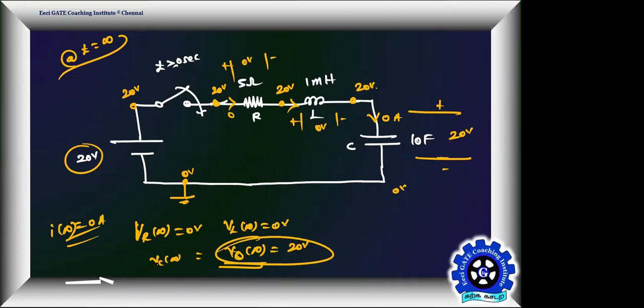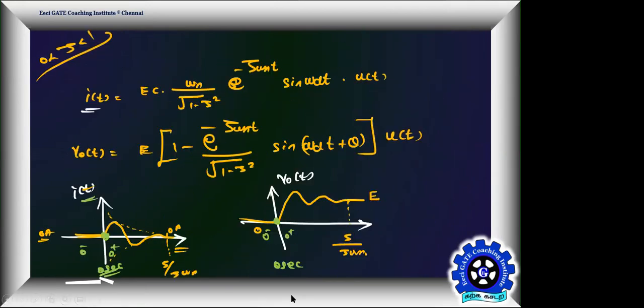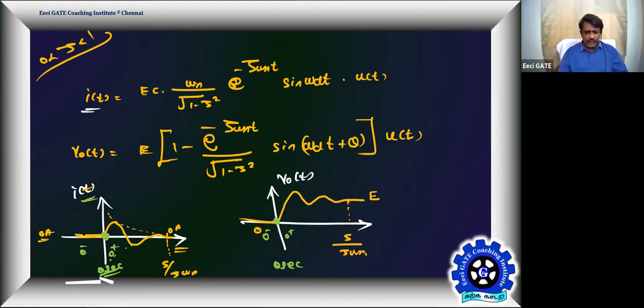Yes, sir. And the waveform is confirming that the current begins with 0 and ends with 0. But in between it has transient oscillations. The reason is that the voltage across the capacitor will change sinusoidally, so the circuit has to obey KVL. Current exists during transient. The voltage across the capacitor will experience sinusoidal decaying oscillations.